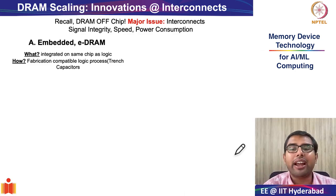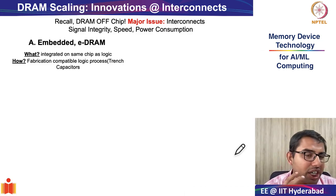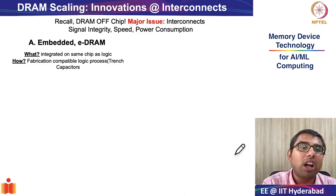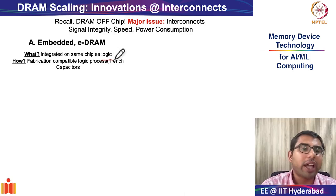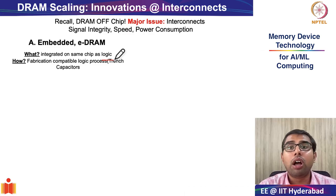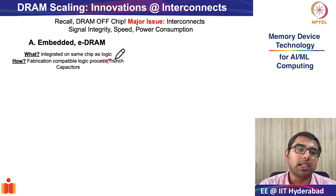So the first technique to remedy this is embedded DRAM, or EDRAM. What is the concept of embedded DRAM? In embedded DRAM, we essentially try to integrate the DRAM process in the same technology or the same processes as your advanced logic nodes. How is this done? You essentially make the fabrication process of your storage node capacitor compatible with your logic processors.